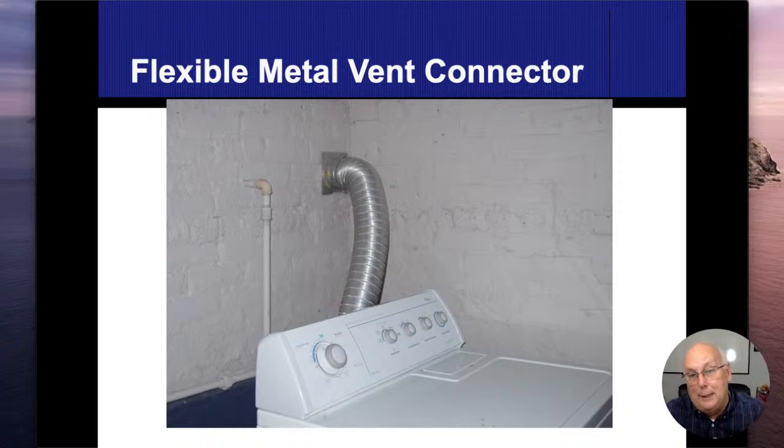Me personally, I really don't have an issue, and I don't call them out. I actually like them better. With these hard ones like this, I've seen people push their dryers back and then they end up smashing the pipe. And once you do that, you've got to kind of throw it away and get a new pipe. With those foil ones, if you smash it, you pull it away, it kind of springs back to normal. So that's another thing I like about it.